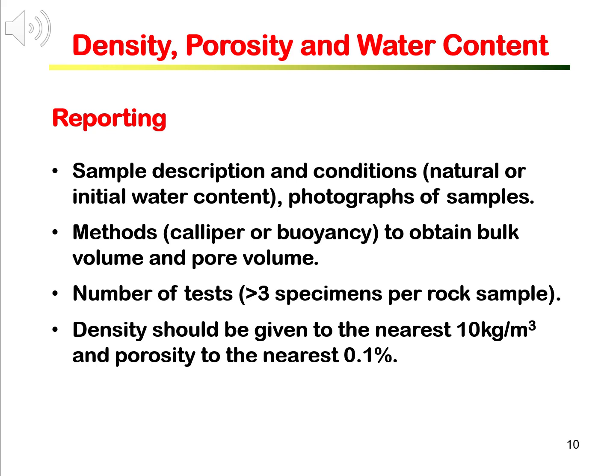For regular shapes, measurements on dimensions should be recorded. For irregular shapes, mass measurements on saturated and submerged specimen should be recorded. All the measurements should be presented in tabulated form.